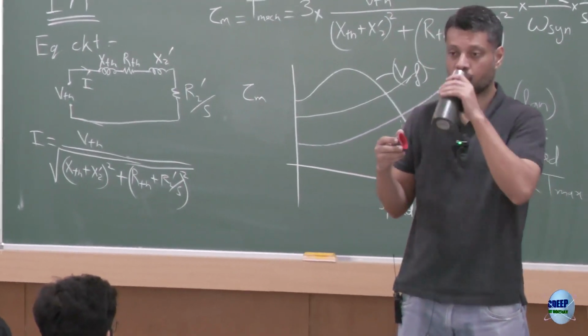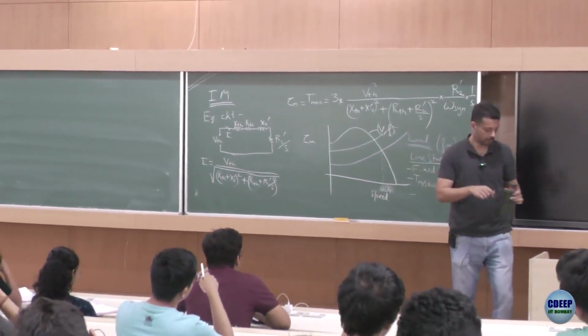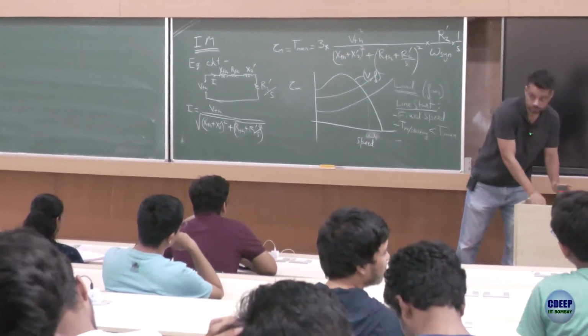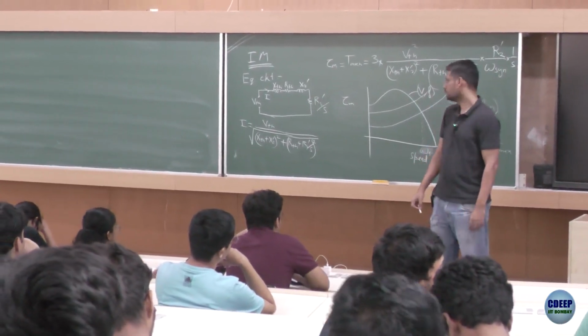If the torque characteristic of a load is above the torque characteristic of the motor at zero speed, then you will never start. Yeah, that is true.